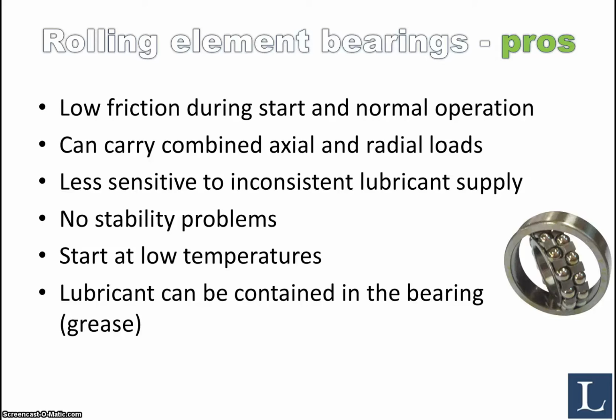And another benefit is that you can also contain the lubricant in the bearing. When we're talking about greases, you can fill the bearing with grease and you can put seals on it, and that will give you what is known as a lubricated for life bearing.